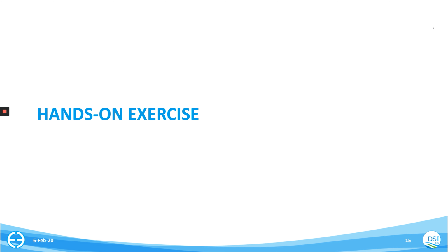You could just add 0.2 meters to every single point in that data. And then the sea levels will all be 20 centimeters higher. And so you could look at what a typical day might look like. Yeah, exactly. You can just make scenarios like that. You can add and subtract from any time series data in the Explorer and just save out the input files again, and you'll be ready to test that new scenario.